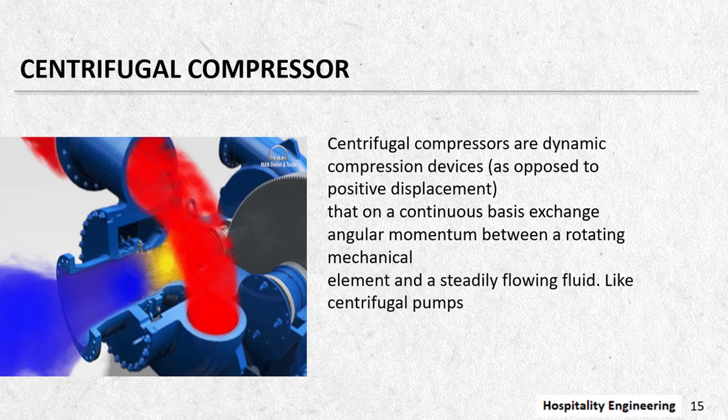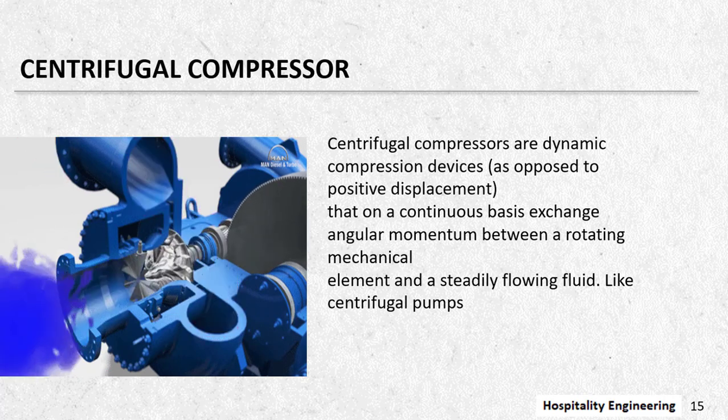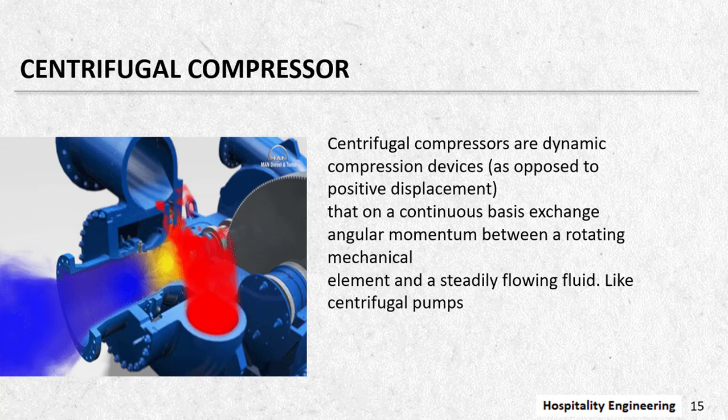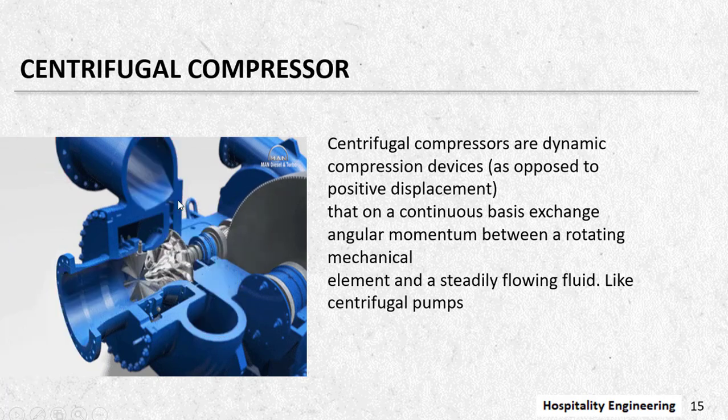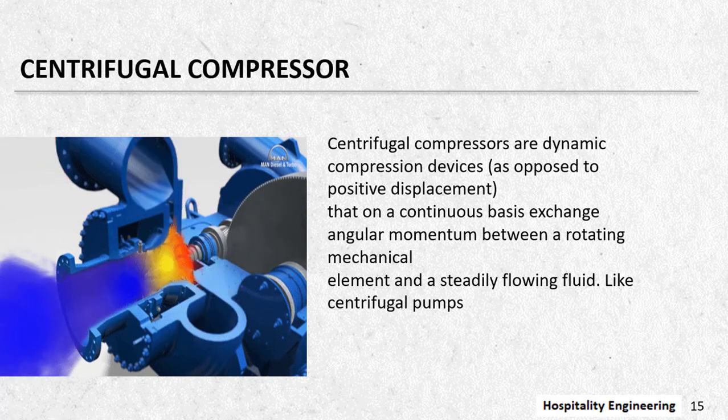In a centrifugal compressor, there is a continuous exchange of angular momentum between a rotating mechanical element and a steady flowing fluid, like centrifugal pumps. You can see there is a blower, the gas comes, then it gets compressed by the centrifugal action, and this red color hot gas goes into the condenser side.